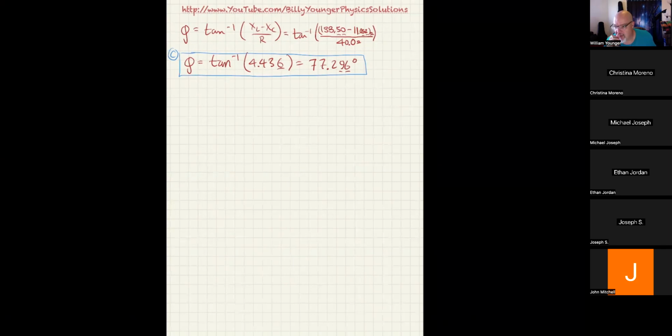Specifically in the real part of that phasor diagram, what we're looking at is the projection of that new vector onto the x-axis. So power is equal to IRMS, which is an equation you should have on your equation sheet, times VRMS times cosine of phi. That's how you're actually going to calculate it.